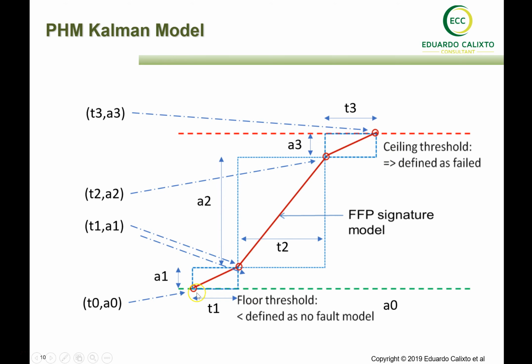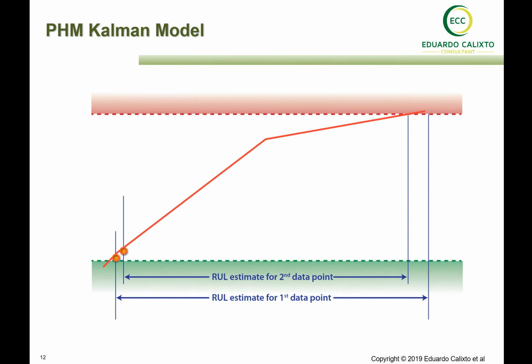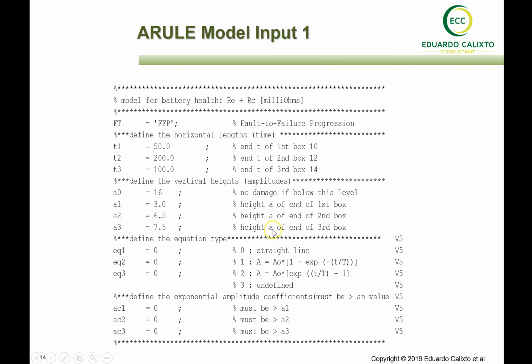That's the beginning. And between these 2 points, we need to define two other points that are the regions that the software will use to adjust the prediction. So this is what we have here: A0, A1, A2, and A3, in percentage, and in the end, we have the temperatures that we consider, temperature 1, 2, and 3. And that's a very important setup to adjust this function.